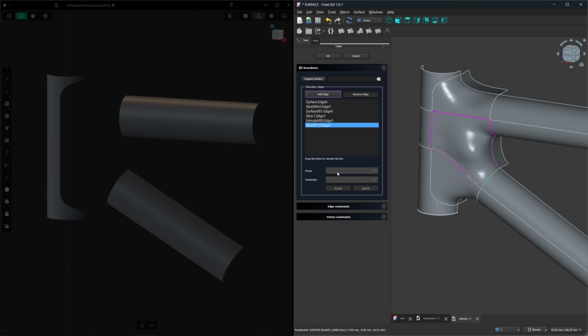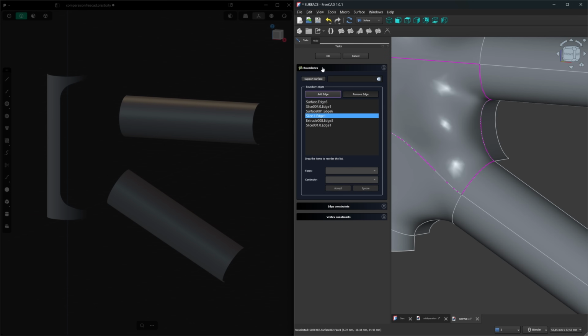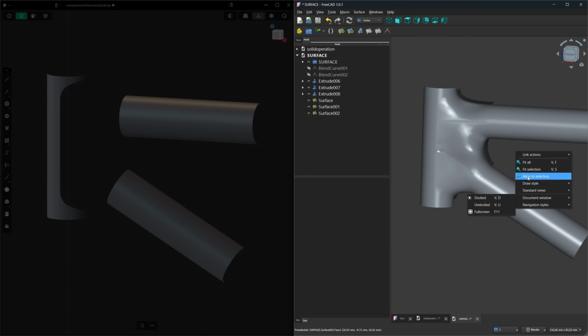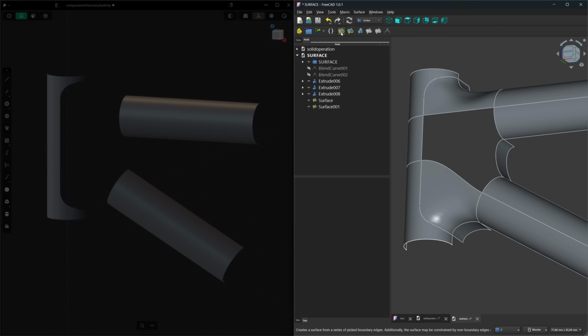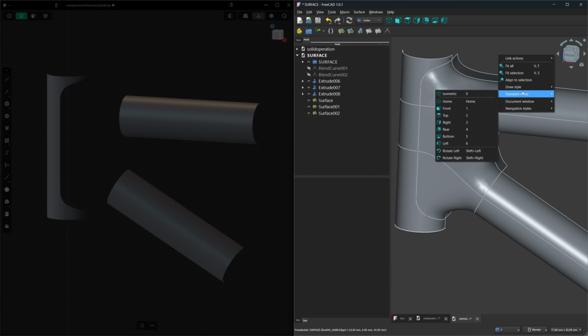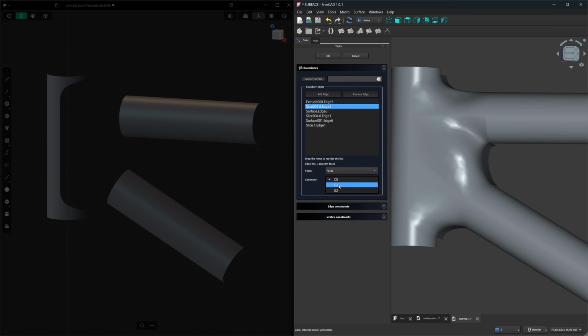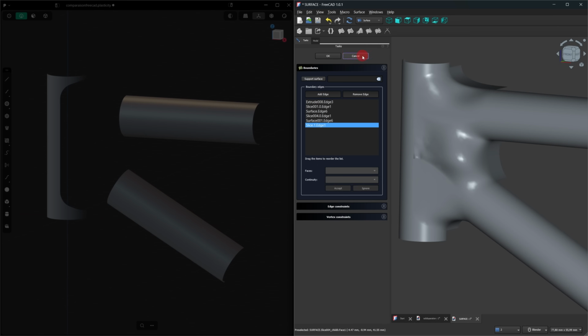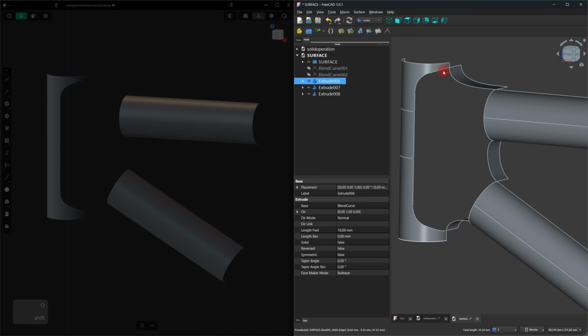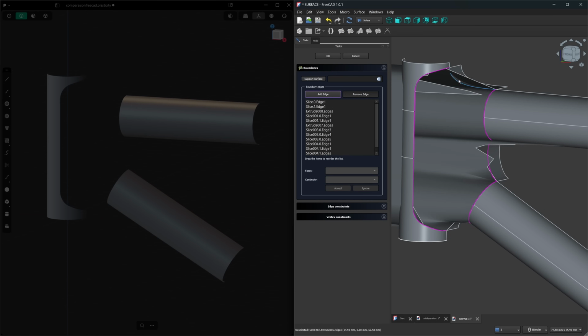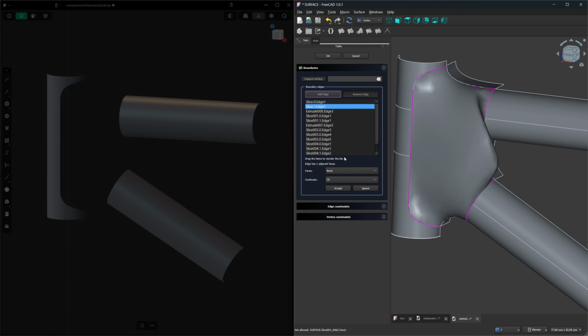I'll continue anyway and fill in the center surface using the same method. But as you can see, the result is far from what we'd expect. Even trying to create a large patch doesn't help. The result is pretty bad. The only way to try and fix this would be to keep adding constraint curves or to simplify the junction altogether. But I know I'm asking a lot from FreeCAD here. It's not really designed to shine when it comes to surface modeling. This case just seems a bit too complex for it.